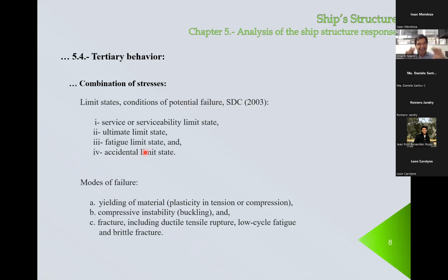So basically, those are the three modes of failure. Some researchers, some engineers like to also consider low stiffness as a mode of failure. For example, you have a tower, and here you have an antenna, right? The wind blows, so the tower deforms. If it deforms, the antenna moves, and if the antenna moves, the connection, because you're receiving a signal, is not here anymore. So you lose connection.